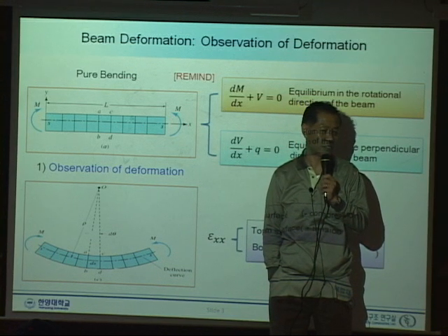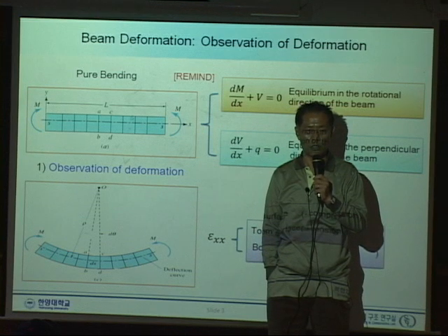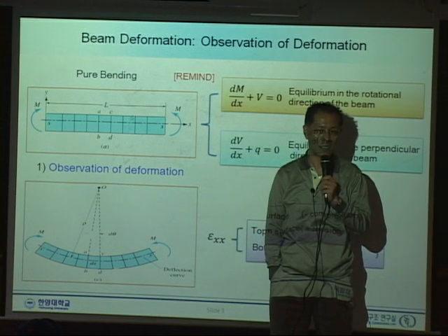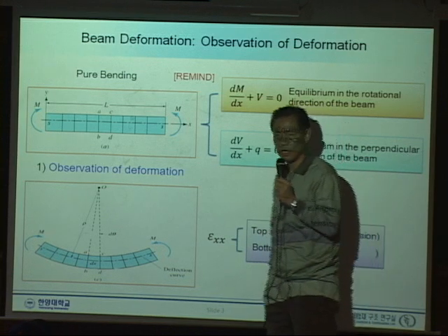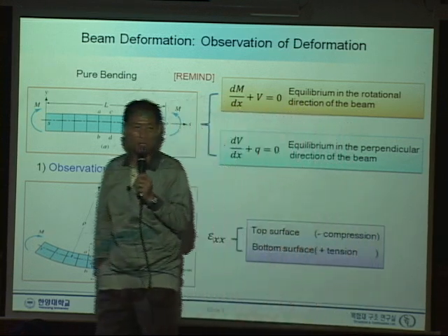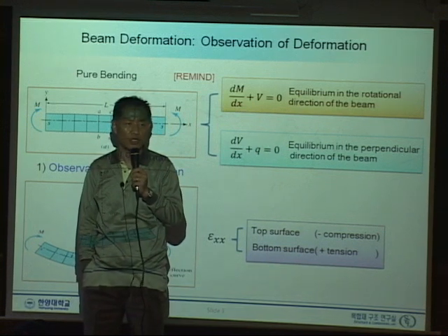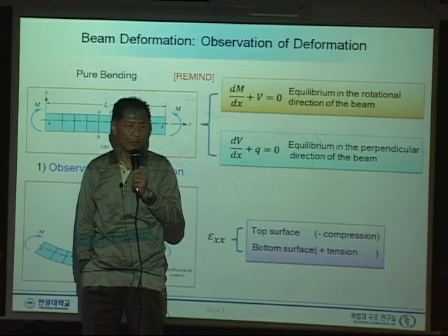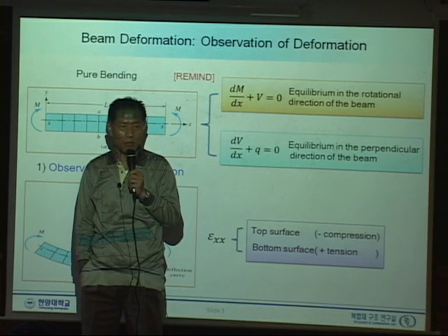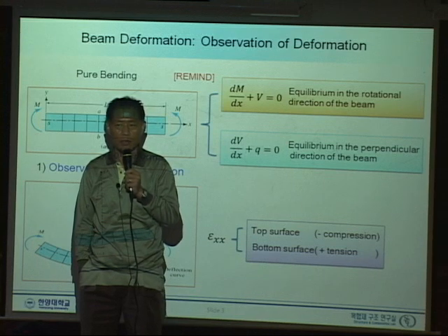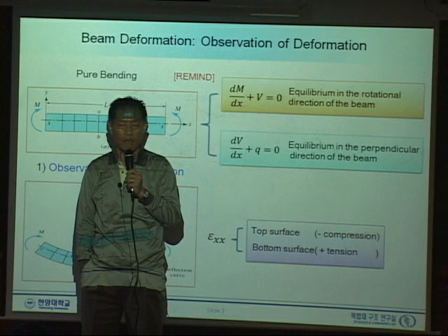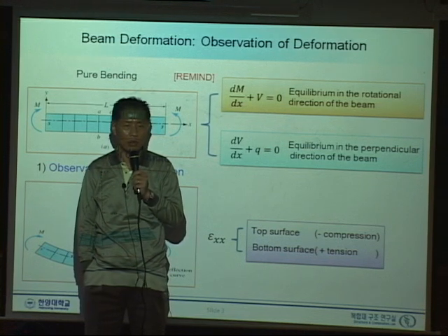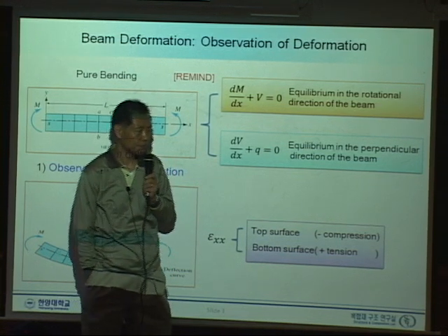Given the force, which is the distributed load Q, a function of x, we derived a differential equation which governs the shear force. So dV/dx plus Q should be 0. And the second equation is from moment equilibrium: dM/dx plus V equals 0. Those are the two differential equations.